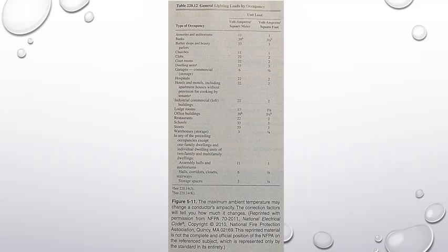Referencing Table 310.15(B)(3)(a), the adjustment factor for 7 to 9 conductors is 70%. The 8 AWG conductor is rated for 55 amps. Multiply this by 0.70 and the conductor is derated to 38.5 amps. Derating is the reduction in ampacity after calculating adjustments and correction factors.